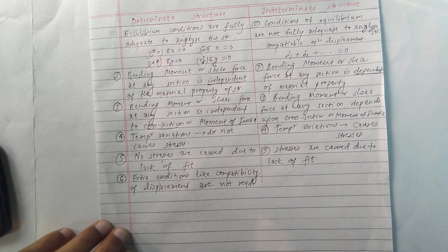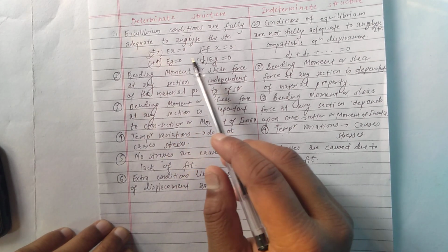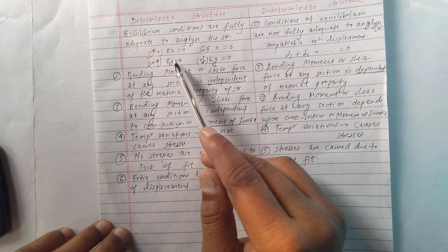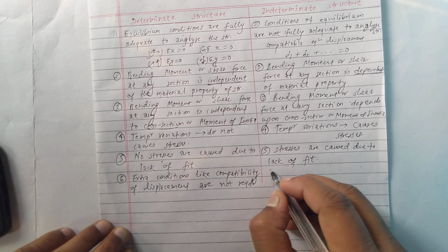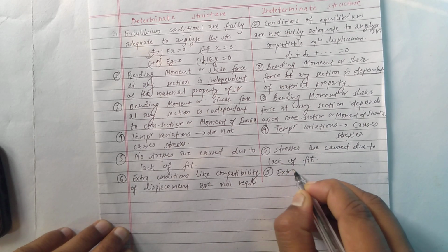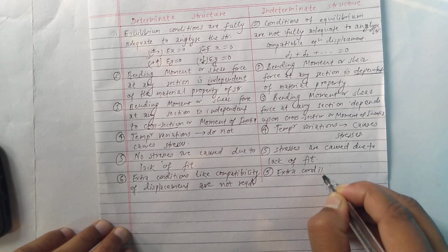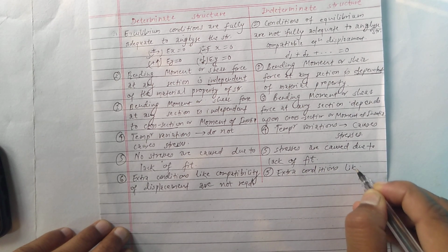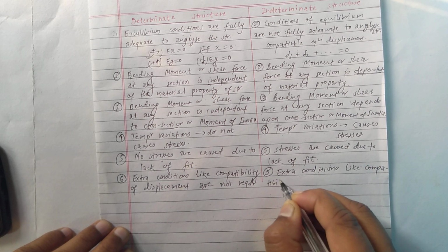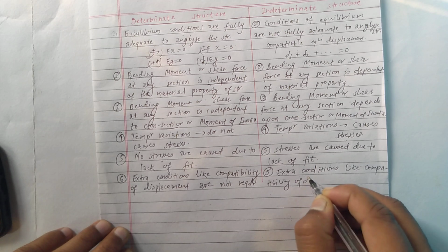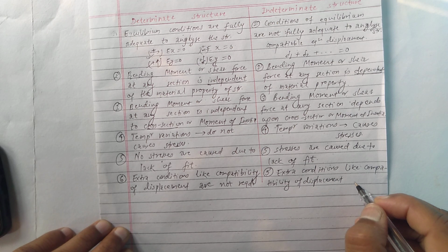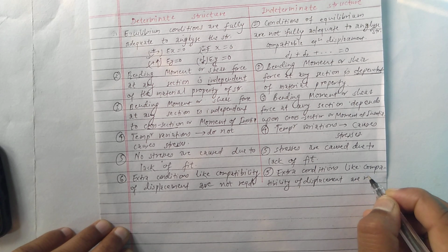Why? Because it can be analyzed with just the basic conditions, that is summation x equal to 0 or summation y equal to 0. But in an indeterminate structure, extra conditions like compatibility of displacement are required.